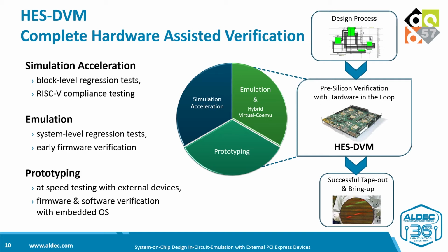Both hardware and software teams can benefit from hybrid co-emulation. Hardware verification team receives a very fast model for running system-level regression tests. Any system integration problems can be traced conveniently in the simulation-like environment because the same test bench is reused during co-emulation.